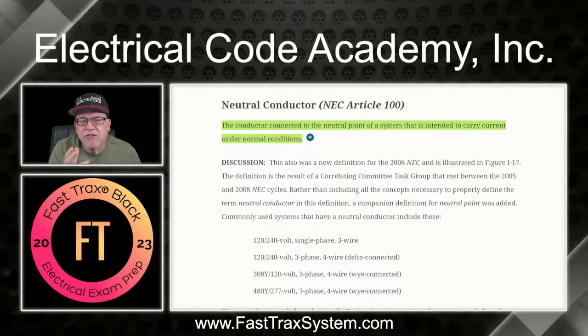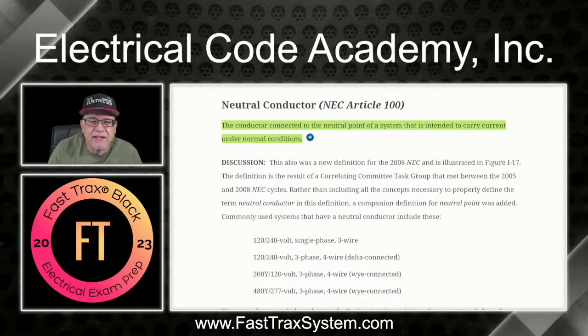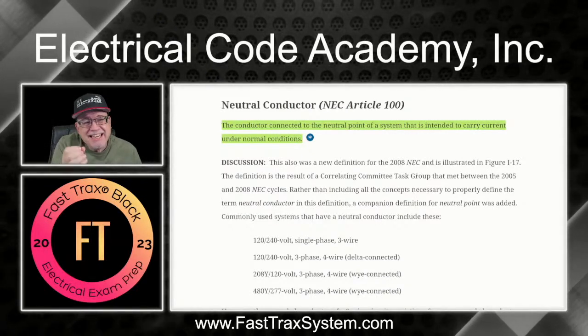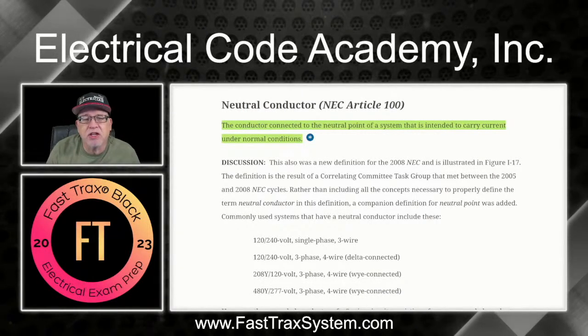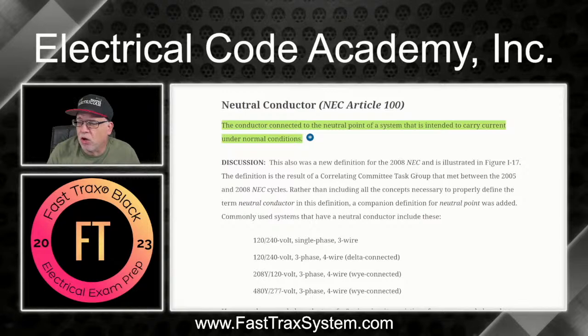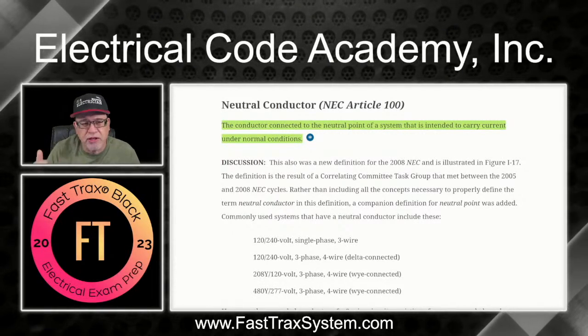what connection creates a neutral. And then it's important to make sure people are aware of what does not create a neutral. Even though a conductor is connected to Earth, based on where it's connected on the transformer, it doesn't necessarily make it a neutral, but it is still a grounded conductor because it's intentionally grounded to the Earth through the system. So all those things are important. They had a task group that got together and created it, and that's what caused them to create the term neutral conductor in 2008. And then, of course, they created neutral point as well. All of these serve to help us better understand it.